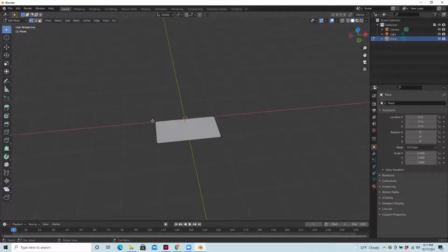So one workflow would be to make changes to some of your points or lines on a 2D surface. And then when you're finished adjusting it, go ahead and add thickness. So if you're still in edit mode, you'll have tools in here to make changes. One of them is called Extrude. And I can grab a surface and kind of lift it up. So what we're going to do is use face select. So I can click on the face to select it.